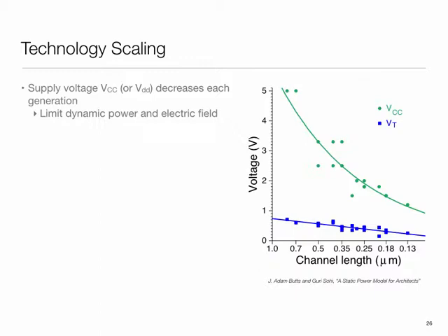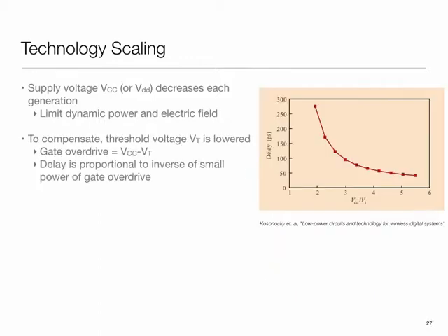The gap between the supply voltage and the threshold voltage affects the speed of the circuit. As you lower the voltage, it comes at a cost, namely things slow down. To compensate for the slowdown, the threshold voltage is lowered. Threshold voltage has been coming down, but there are limits to how far you can go, and like I said, it has plateaued.